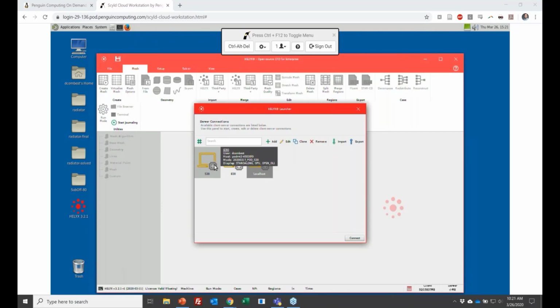If I was doing a much larger job, I would simply click on this, work through the GUI, set up my mesh, set up the case, and when I submit a job to mesh, it will submit directly to those queues, which is very nice. It selects how many nodes we need, so you don't need to go down to that fine-grained level and select how many nodes. These two run modes, as we call them, can be provided by ENGYS support to users on pod.